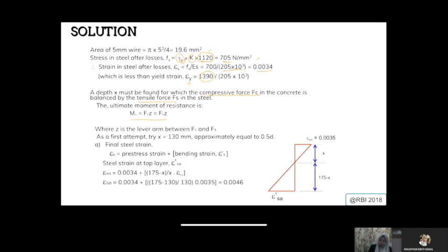So you will take these values, and as a first attempt, you try X is equal to 150 mm. So why first attempt 150 mm? At this point, you don't really know where the location of your X is. As we know, you are given the section, which has a height of 300. So if you look in general, you will see that it will be half, like 150.